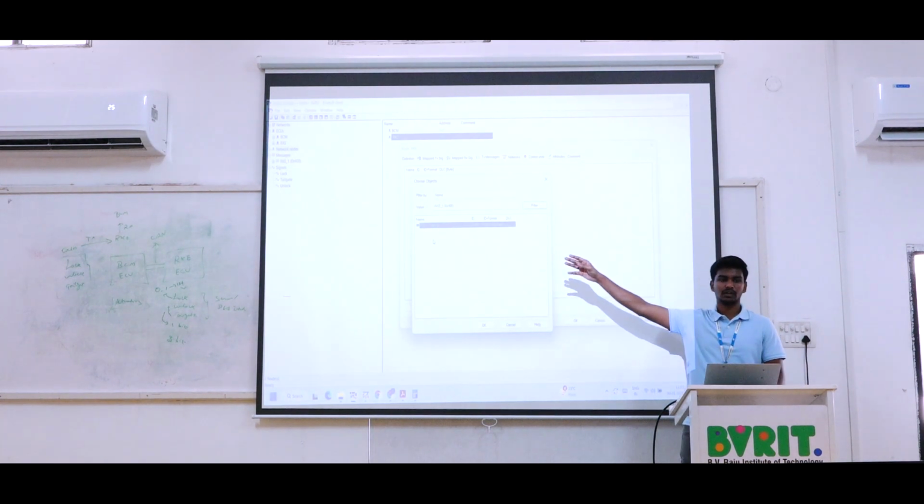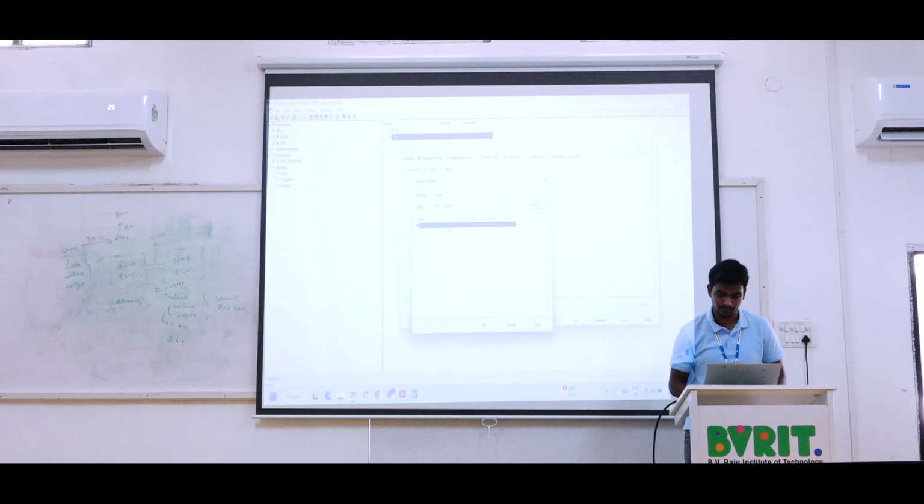But later we will create more than one, like 20 messages. So then we need to select the particular message, ID number 400. Then give OK, and it shows the message values. ID number 400, standard format, it has a DLC value of 3. And then you have to give the update.